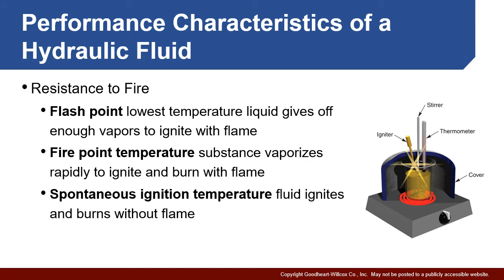Another characteristic of hydraulic fluids that we need to consider is it's resistant to fire, either high temperature or flame. The fact is there's a number of different temperatures that we need to consider. It's also important to realize that the most common type of hydraulic fluid we use is petroleum-based, which is clearly flammable. If we look at the flash point, it is the lowest temperature at which the vapors are going to ignite. It turns out that anytime you have a liquid, there's a certain amount of vapor that is consistently going to be coming off of that. It's going to be vaporizing. That's what evaporation is. It's that oil or any liquid converting over to vapors.